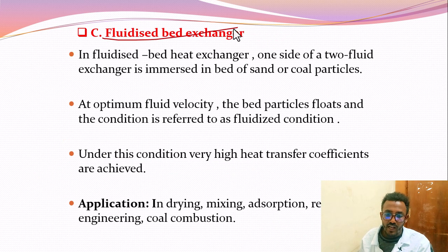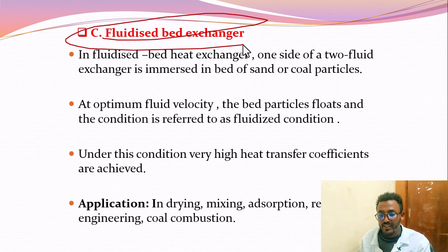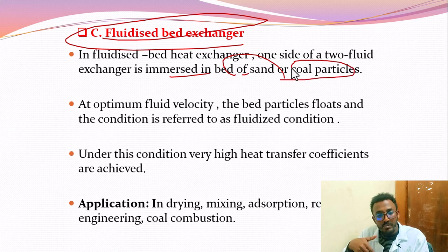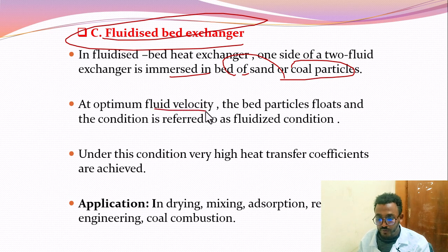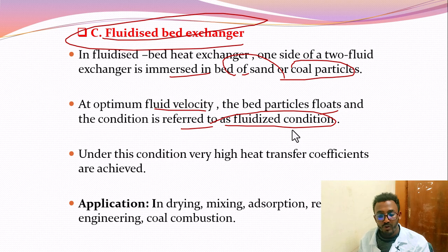The other one we have is fluidized bed heat exchangers. In fluidized bed heat exchangers, one side of a two fluid exchanger is immersed in a bed of sand or coal particles. At optimum fluid velocity, the bed particles float, and this condition is referred to as the fluidized condition.